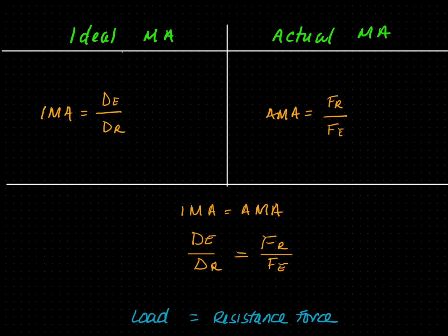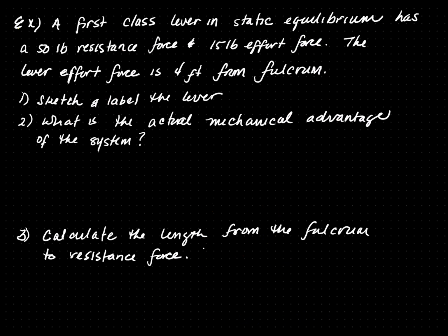We could solve for one or the other by setting IMA equal to AMA, so DE over DR is equal to FR over FE. Remember, load is the same thing as resistance force. Input is the same thing as my effort force. Pause the video and see if you can solve these problems and then check your answer.